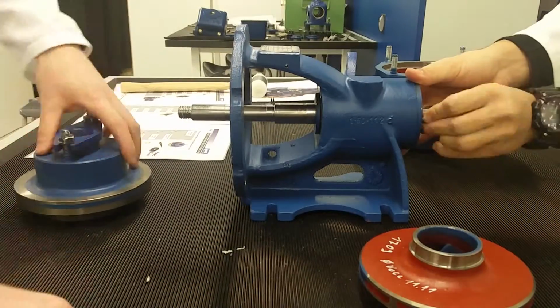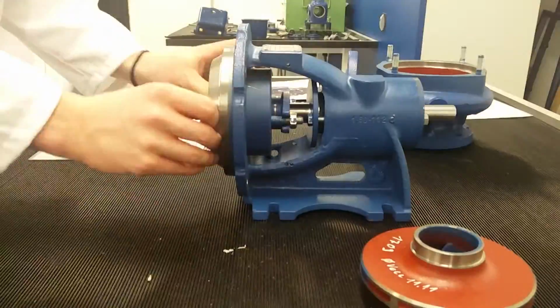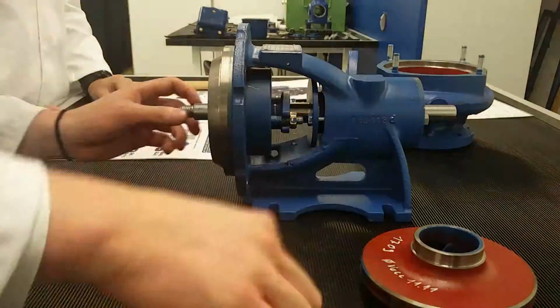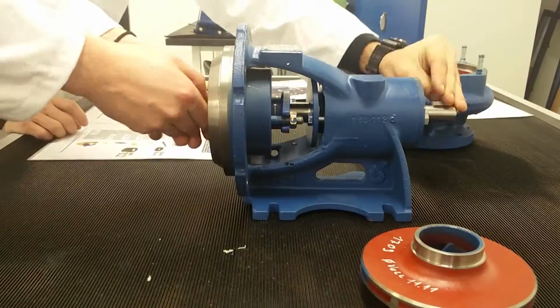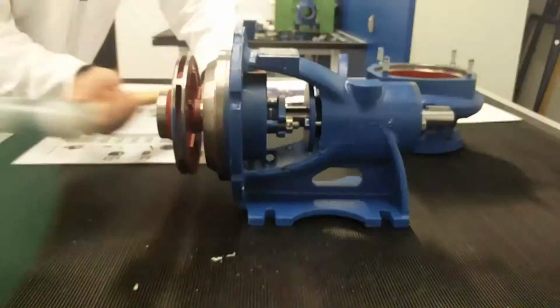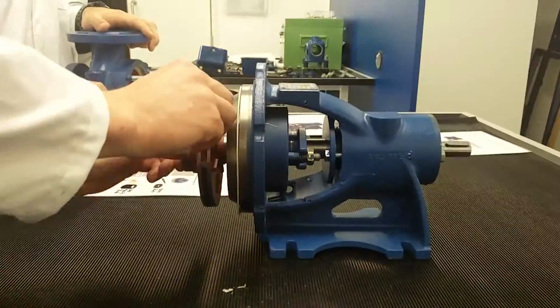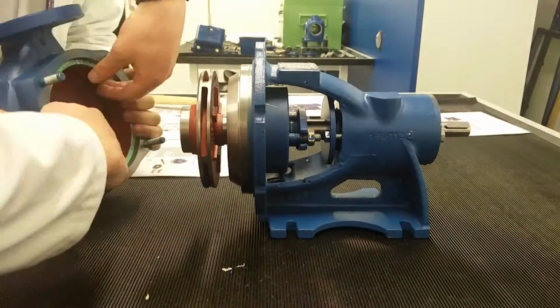Constructing the centrifugal pump begins by securing a cover to the back of the pump, followed by attaching the impeller to the front by securing it to the shaft. A small piece of metal called a feather key is fitted within the shaft and holds the impeller in place. The casing is attached around the impeller with the discharge nozzle facing upwards and at 90 degrees to the inlet flow.